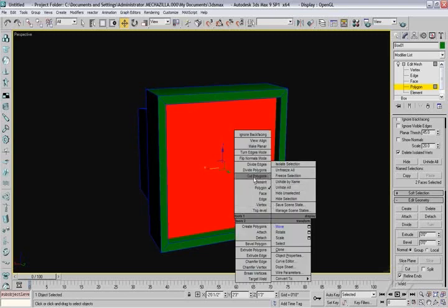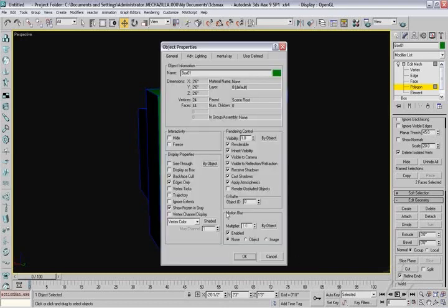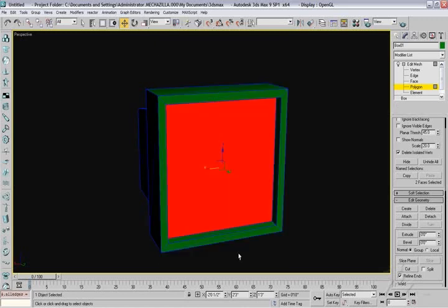And again, it's called a quad menu because there are 4 quadrants to this. Down under the lower right hand quadrant, navigating down, you will find something called Object Properties. Go ahead and click on the Object Properties, and this will bring up some things that we can do, like displaying all the invisible edges. Now remember, as I said, everything is still made up of triangles, but the difference between a face and a polygon is what's visible and what isn't. So go ahead and uncheck the Edges Only button, and then say OK, down under the Object Properties.